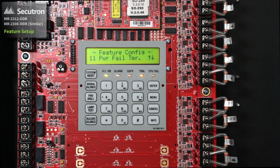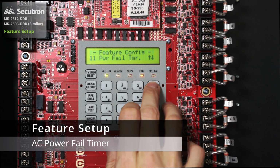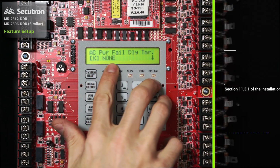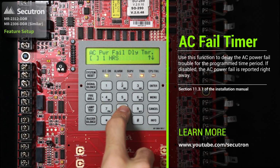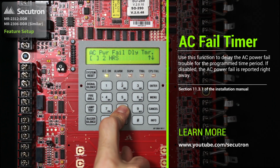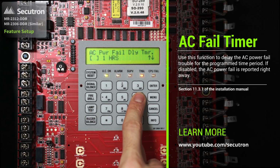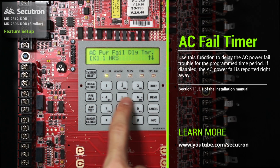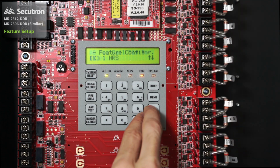Our next option is the AC power fail delay timer. By selecting this option, we can have it set for default, which is none, or we can scroll through for 1 hour delay, 2 hour delay, or 3 hour delay. Once the desired delay has been seen, we can press the left or right cursors to apply the X, and that will change the AC power fail delay timer.